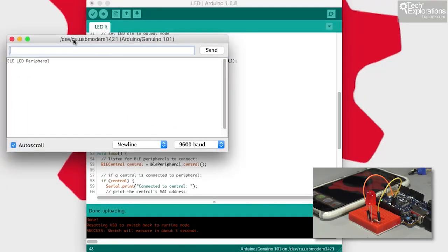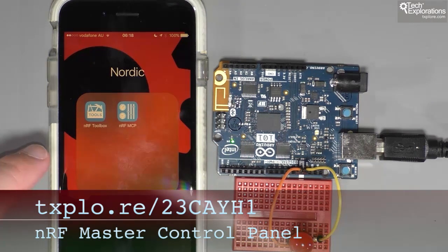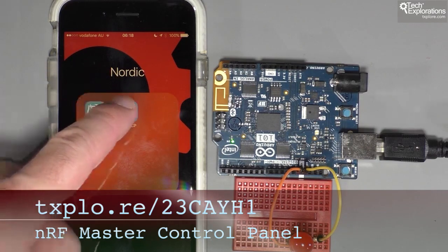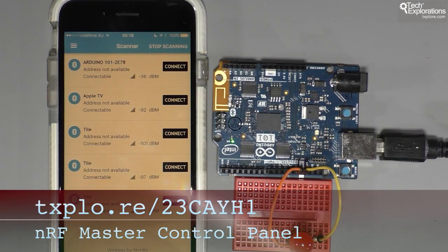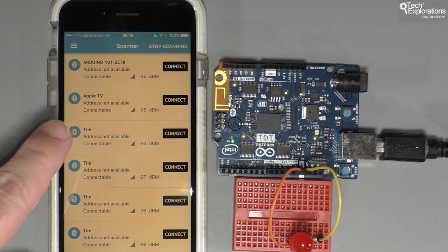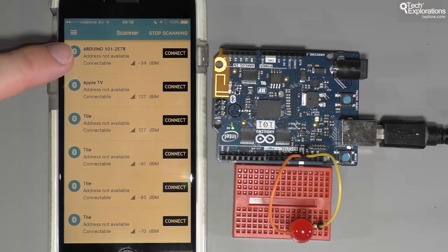Right, so we've got BLE started on the Arduino 101, and to see what's happening and actually turn the LED on and off, I will use the nRF Connect application. It's one of the Nordic Semiconductor applications that allow you to play around with BLE modules. So I've got my app running, and you can see that the first option here has been detected.